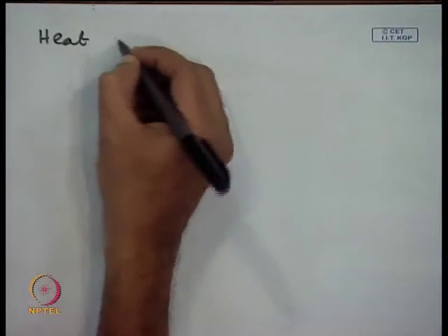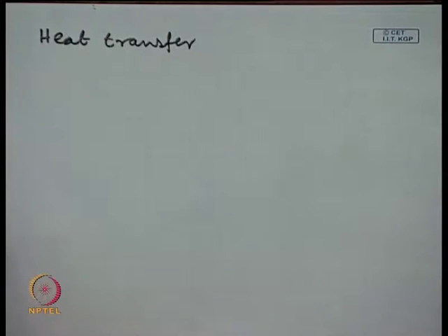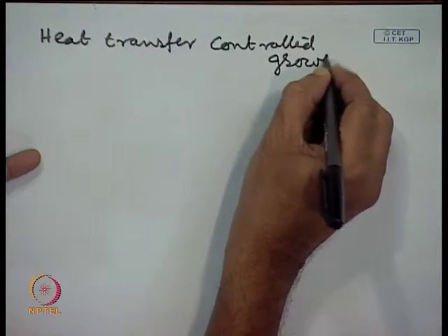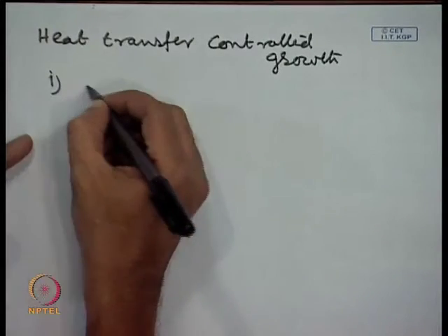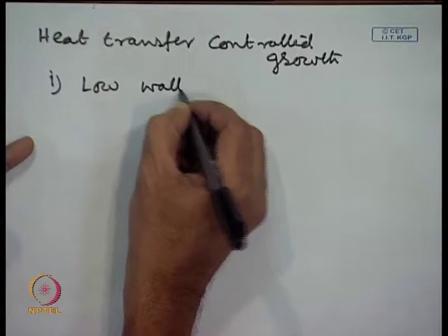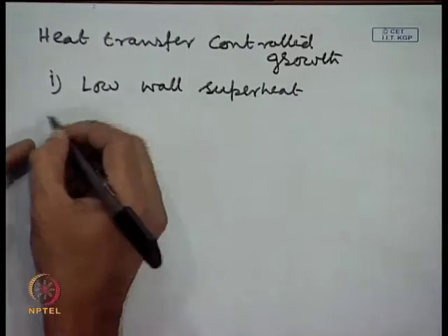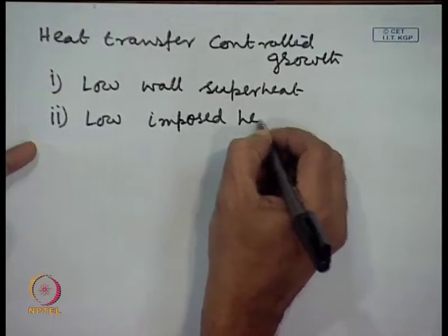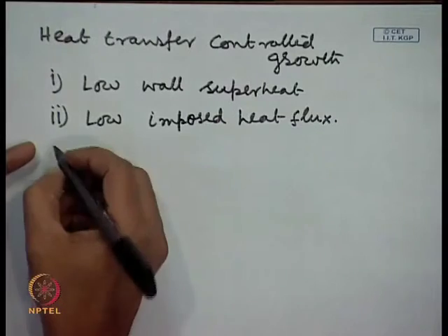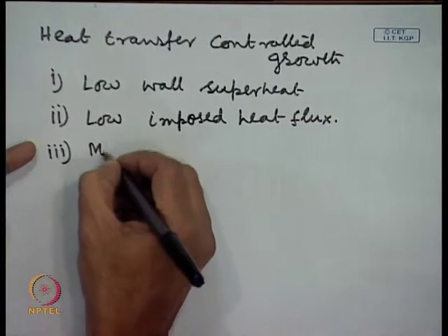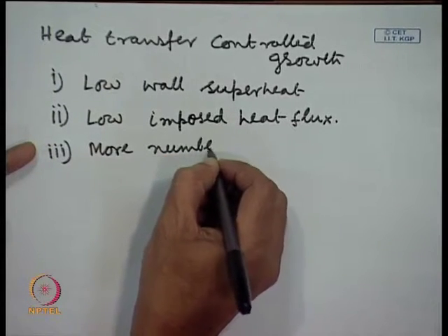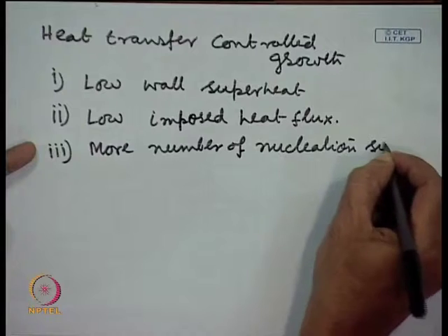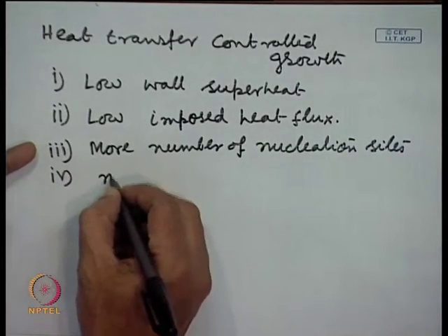So, we can quickly write the condition. It will be low degree of superheat or low wall superheat, low imposed heat flux, more number of nucleation sites, non-wetting fluid,